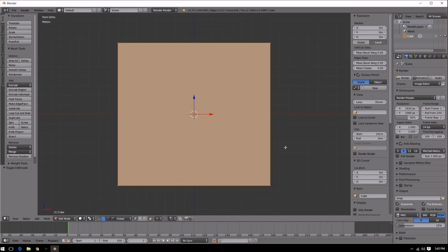You can snap to edges of meshes, you can snap to vertex of meshes. But what we're going to do is stay in the increment so that we can actually use these grid lines and stay very even and very accurate with where this mesh goes on this screen. So now that we're in edit mode, now that we have the whole mesh selected, we're going to hit our grab key by hitting the G on the keyboard.